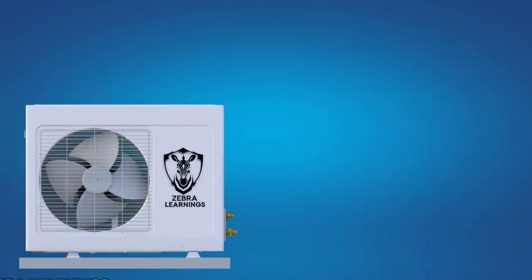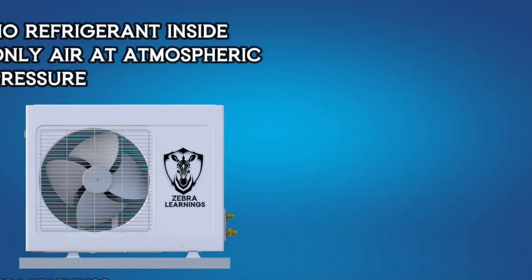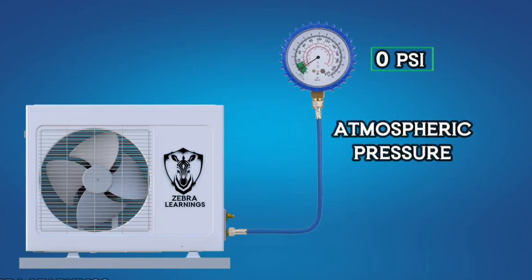Let's take an outdoor AC unit as an example. There's no refrigerant inside, only air at normal atmospheric pressure, which is 14.7 psi absolute. Now, if we check the pressure using a manifold gauge, it'll still show 0 psi. Even though the actual pressure inside the unit is 14.7 psi, the gauge reads 0 because it treats atmospheric pressure as the 0 reference. To understand this better, let's see a few more readings.